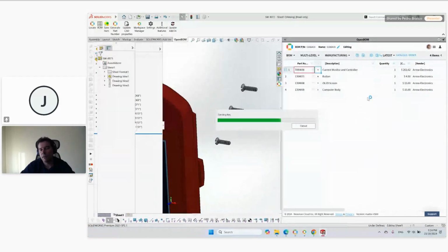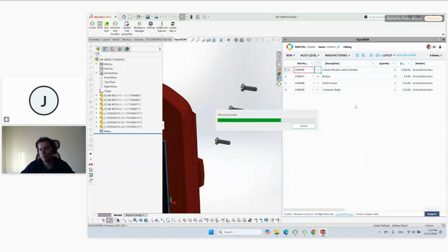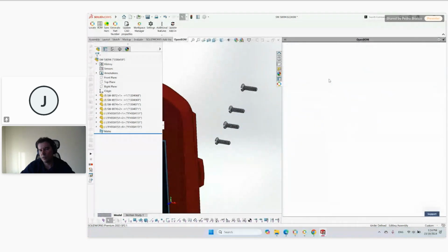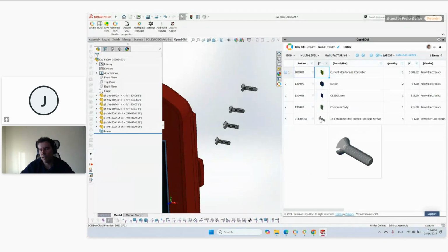And you can see that it refreshes the four items in the bill of material just inside SolidWorks. So this integration inside SolidWorks is going to update. And you see the four bolts just being populated there. You can increase a bit the thumbnails here. There they are. And notice that that item that I added manually was not removed. So we merged changes. If you add non-model items like lubricants or seals, packaging labels, all that, we distinguish them.